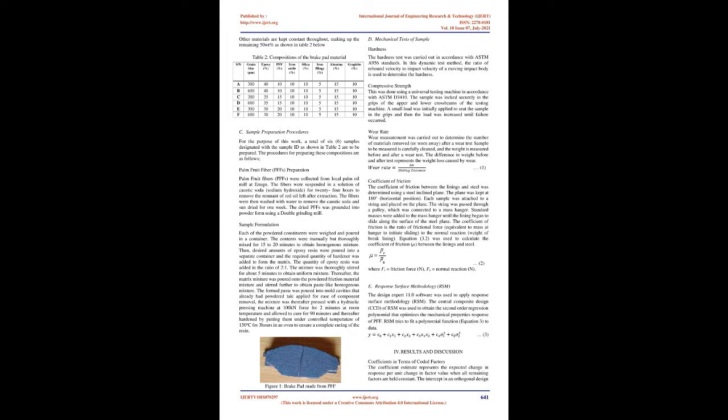brake pad manufacture. Performed a tribological study to improve the performance characteristics of the friction product, brake pad, by using steel wool, a metallic material which has an excellent structural reinforcement property and high thermal stability, which are indeed required to improve the performance of the brake pad. Under the study, 5 frictional composites were developed and optimized using the same ingredients in an appropriate proportion except steel wool, 0%, 4%, 8%, 12%, and 16%, which is compensated by synthetic barite, and the synthesized compositions are designated as